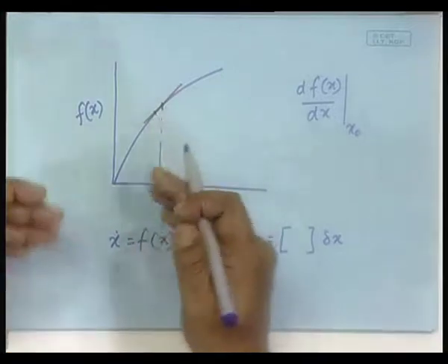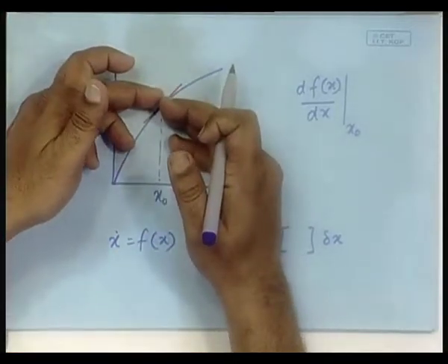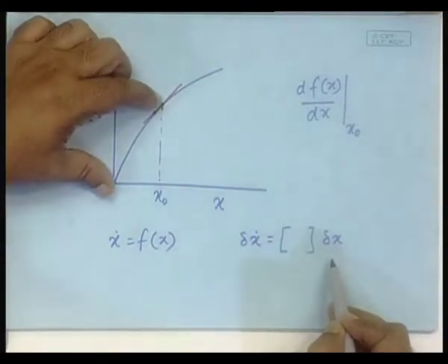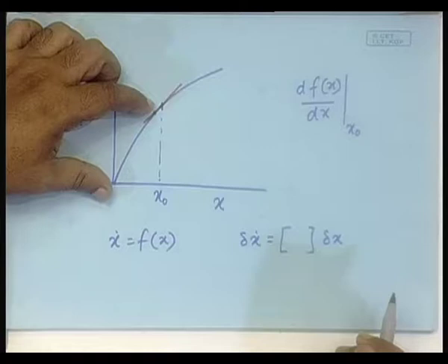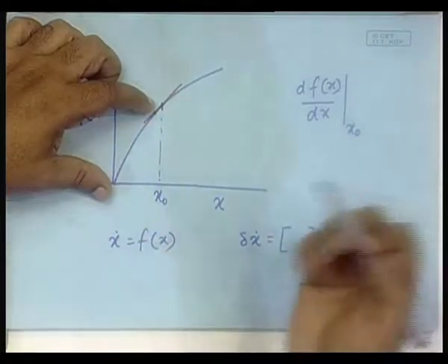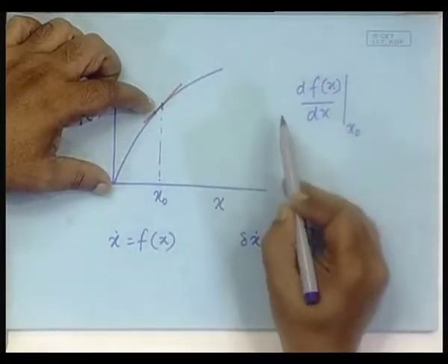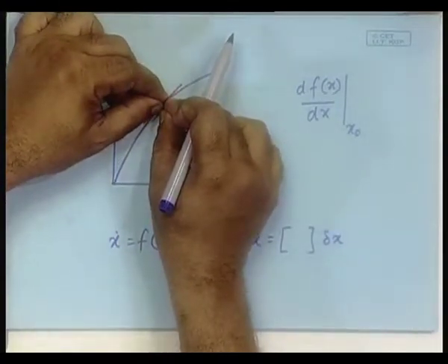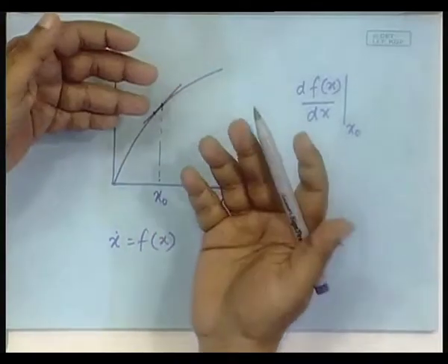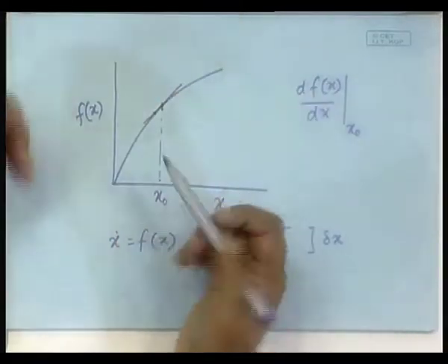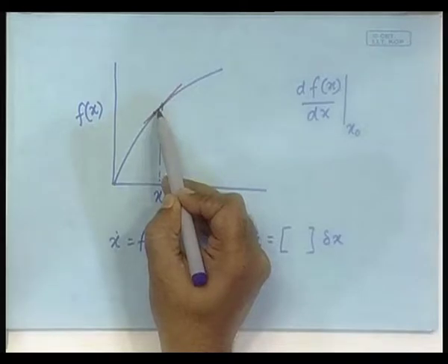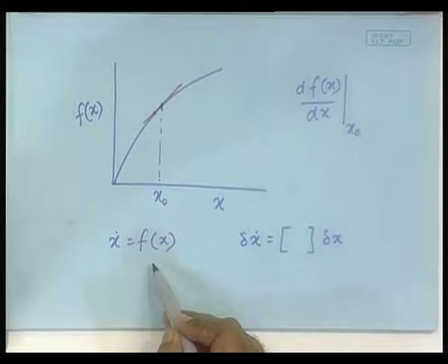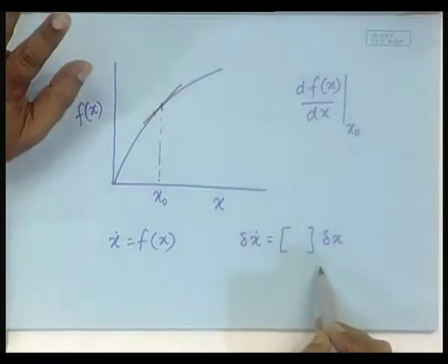In other words, your origin shifts to this point in the new representation. The origin shifts to this point. That is a vital issue that some people miss while developing the understanding. While you are doing the local linearization, you have to move the origin to this point around which you are doing the local linearization, and then the variable becomes the deviation from that point, not the original one, and then only this local linearization will be valid.